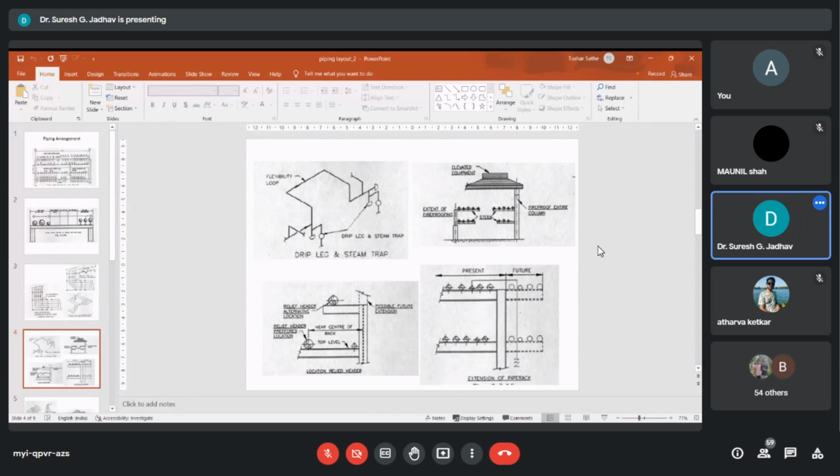And we have discussed the valve location. So here we have to consider the valve location. That is, accessibility to valves and instruments should be the primary concern while arranging the piping. The process isolation valves should be readily accessible, at an elevation of 1200 to 1500 millimeters from the ground, that we call the operating level. If at elevated levels, they can have chain operators.